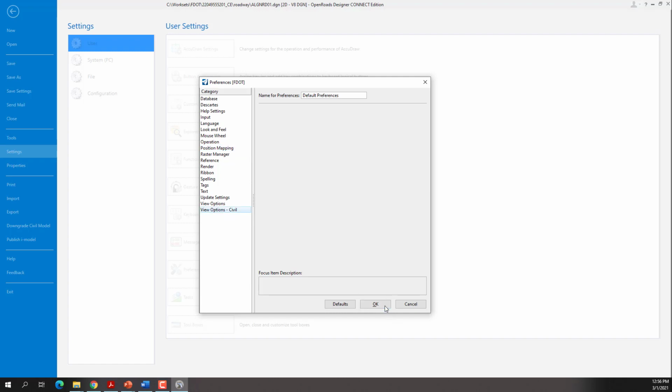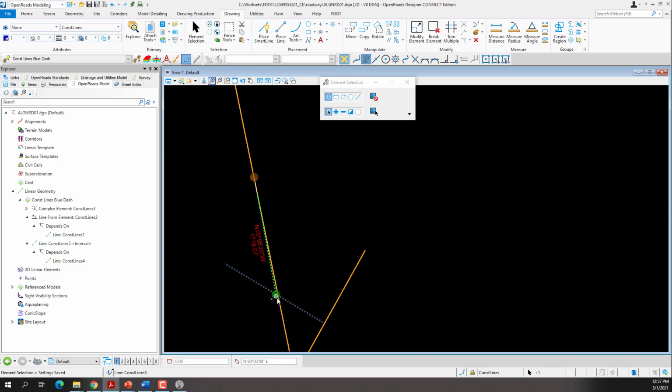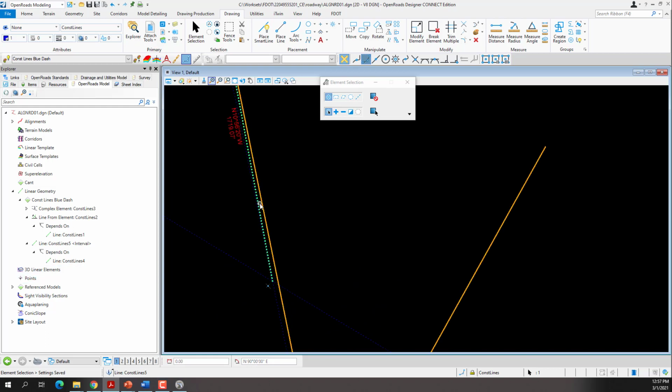So click on that. I will do Save Settings. Come back in, and now if I select on that, it's going to make that much bigger and easier to see. So that's an interval on that. So now if we move all these lines, everything will come together. That's what the next exercise shows, but I'm not going to go through it. So we're at construction line 5, 6. We want to place, or need to place, the arc between construction line 2 and what is now construction line 5. But we want to apply our design standard first.